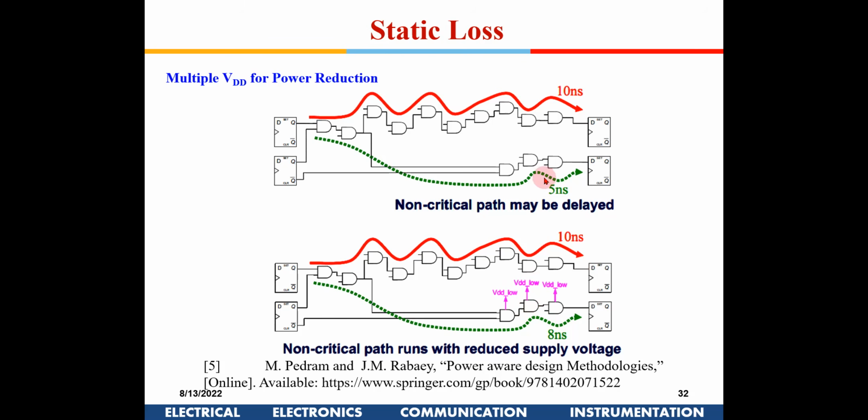No, we will not talk about hold violations out here. Because if you see here, this is like the next clock. The clock is set as per 10 nanosecond. This was reaching here at 5 nanosecond. I am talking about setup time of these two flip flops.